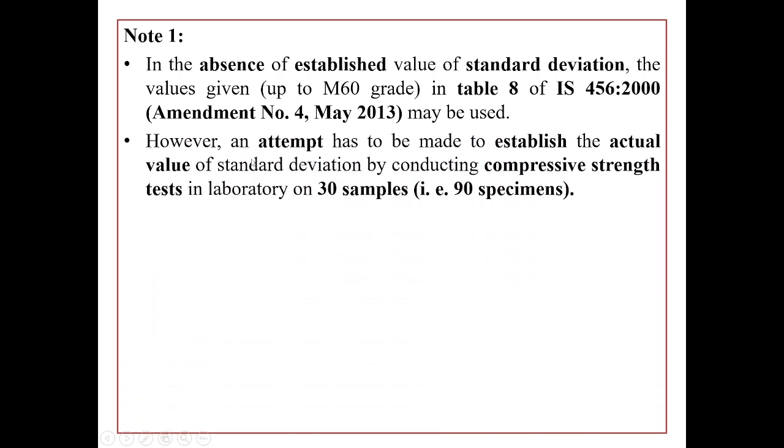However, it is always better to make an attempt to establish the actual value of standard deviation by conducting compressive strength test in laboratory on 30 samples. That means 90 specimens.